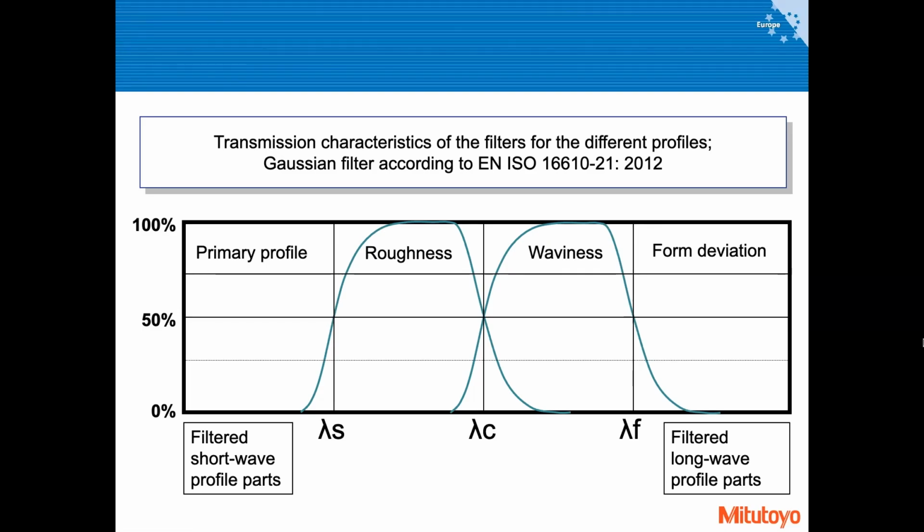Because if you choose this cutoff value randomly, just out of the blue sky, there's almost no chance to do repeatable measurements. Because if the person who, let's say, produced this part chose the cutoff value, and you choose your own, it will very dramatically change the overall profiles you will obtain. But this will be mentioned further on and shown in examples, and I hope you will all understand very well.